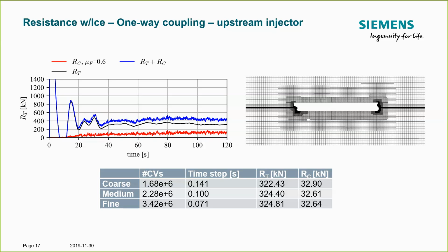Actually, it can be shown that if you only refine in one dimension, you can arrive at basically an invalid discretization study that will not give you the opportunity to extrapolate based on, for example, Richardson extrapolation.